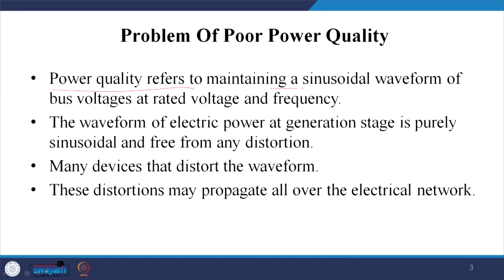So, let us talk about the problem of power quality. We want quality power. Power quality refers to maintaining a sinusoidal waveform of bus voltages at rated voltage and frequency. So, you should have a constant frequency and proper sinusoidal voltage and current with constant magnitude. Then you can say that we are getting good quality power.